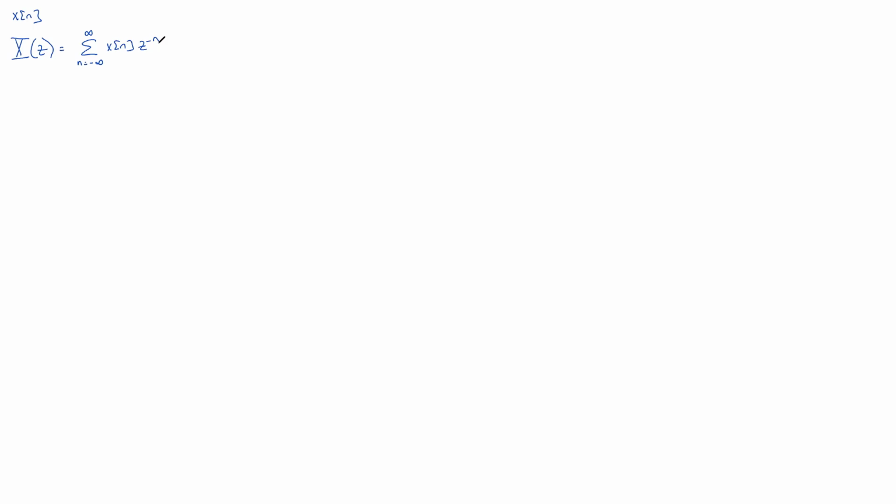It's easy to compute. If I'm doing any kind of theoretical work with a signal, I'm going to use the Z transform because this is the simplest to manipulate. It also converges for the widest possible number of inputs. Remember, the DTFT doesn't exist for a lot of things. The sequence 2 to the n has no DTFT. The sequence 2 to the n has a Z transform.